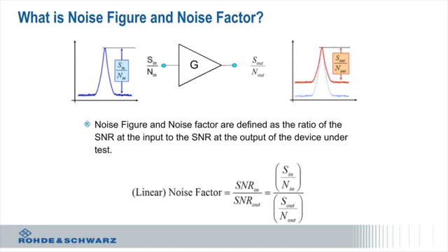While noise added from more modern technologies is very low. You see receivers that have LNAs in them that might be in tenths of a dB, which is unheard of going back to sort of the 60s or 70s. In fact, I had a colleague I worked with who got his PhD in the 70s designing an LNA that had a noise figure of 12 dB. So by today's standard, that wouldn't be very good. We're now in the tenths of dBs.